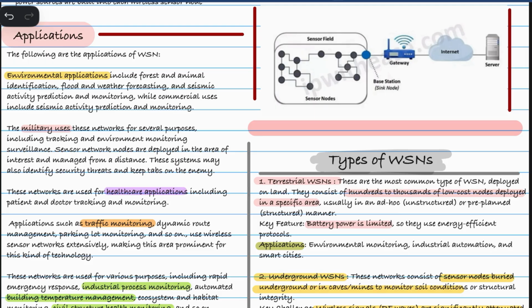It also provides resilience and fault tolerance. If a wild animal destroys a sensor, right, what happens? The network shouldn't crash. The remaining nodes must dynamically find a new path to route the data around that dead node. And then it is also required to scale, to provide scalability. For example, your network needs to expand from 10 nodes to 10,000 nodes. It should be done seamlessly without rewriting the entire architecture. So that is why WSN is very important and unique from a Wi-Fi network.